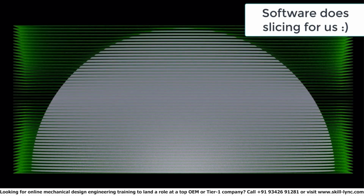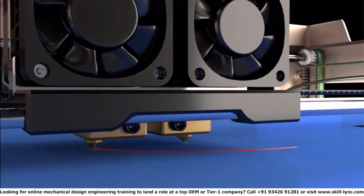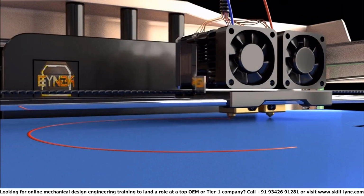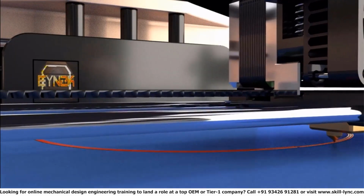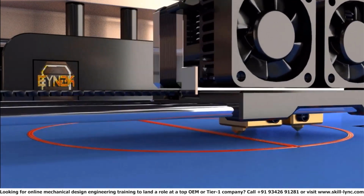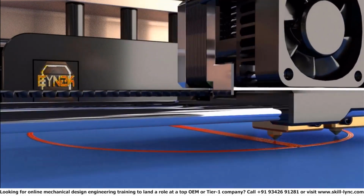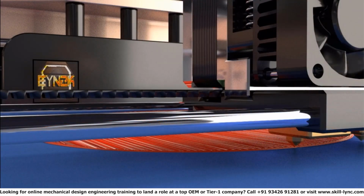If your 3D printer is a bit more expensive, a bit more advanced, it can have two nozzles, so you can feed two types of material through it, one for the main model and one material just for the support structures. And the support structure material can be a bit, let's say, weaker, so it's easier to remove in post-processing, or there's some thermoplastic filaments that have an element of water solubility to them, so pretty much they get softer, weaker, they start to dissolve in contact with water.